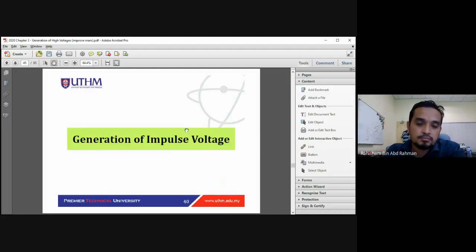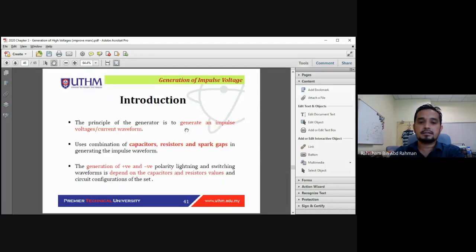As I explained to you earlier, it is solely for testing purposes. To test our dielectric strength, to test the power equipment and protection devices, so that we need to simulate the impulse. We need to simulate lightning or switching impulse with the impulse generator.